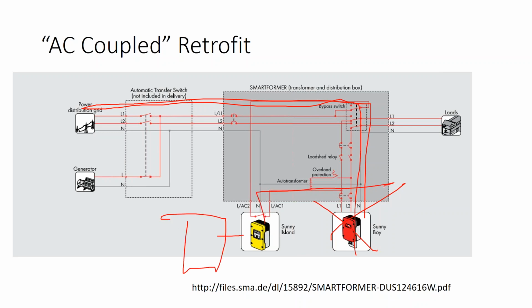Just land it on the same panel as the solar array, and there's some additional things you need to do. This battery is hardwired into the grid as well. And just like with a generator, it wants to power your load, but it can't backfeed the grid. So when you get into battery design, you're dealing with transfer switches that will disconnect the home from the grid so that your solar and battery banks can be active.